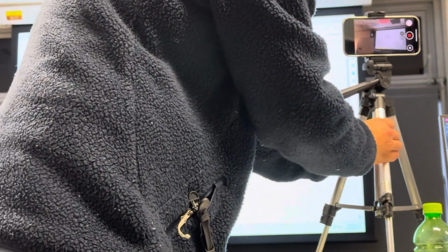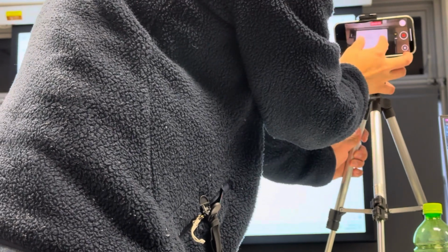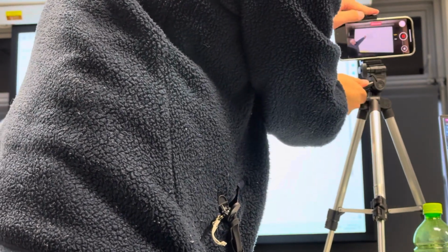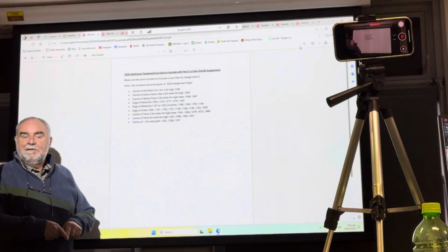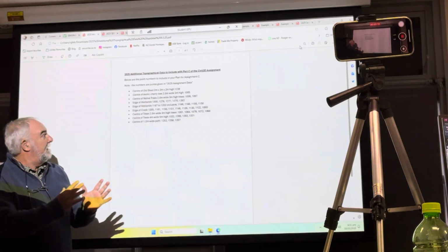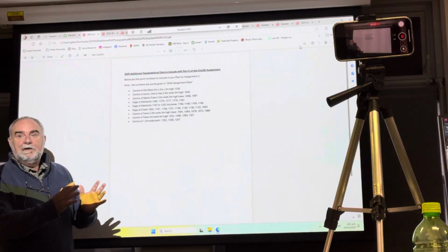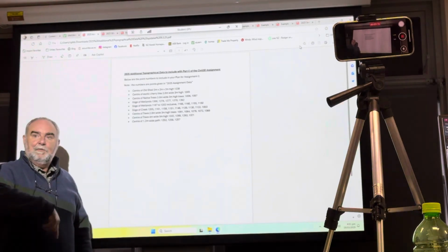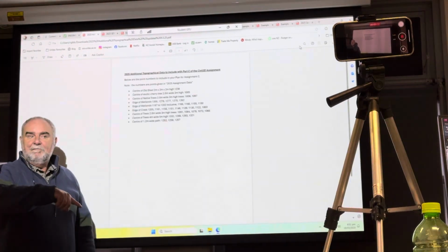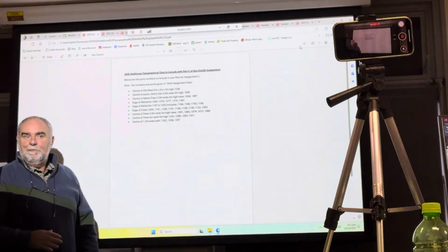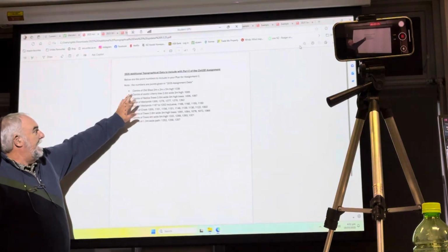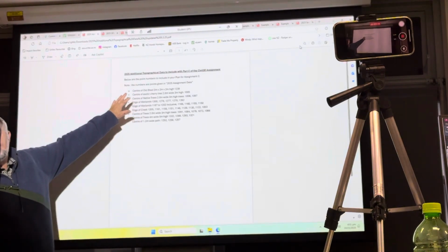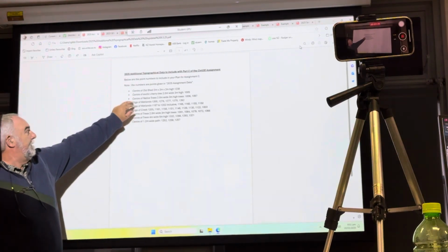So, this file is in assignment 1. You've got a centre of a shed on point 1238. So you're going to have to draw that in AutoCAD. But be aware that it's 2 metres by 2. So if you did a circle 1 metre diameter, then that'll make sure your road misses that. You should miss the shed as well, unless it's in the road, in which case you may have to look at trying to get rid of it.